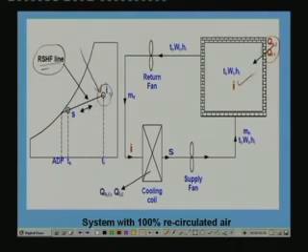Once you know the slope of the line and this inlet state I, then you can draw this RSHF line, and the supply air condition must lie somewhere on this line. It cannot lie anywhere else. If it is lying anywhere else, then it cannot take the sensible and latent heat loads in the required proportion. So if the air has to take these sensible and latent heat loads in this required proportion, then it must always lie on this RSHF line.